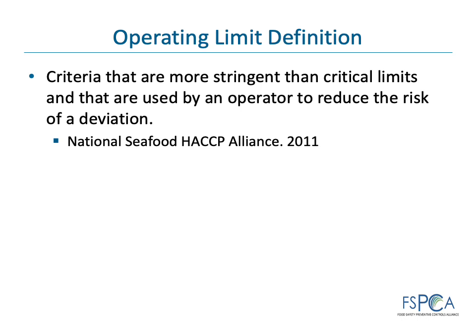The process may be adjusted when the operating limit is not met, which avoids violating the critical limit. These actions are called process adjustments. A processor may use these adjustments to avoid loss of control resulting in a deviation and the need to take corrective action. Spotting a trend toward loss of control early and acting on it can save product rework or, worse yet, product destruction.